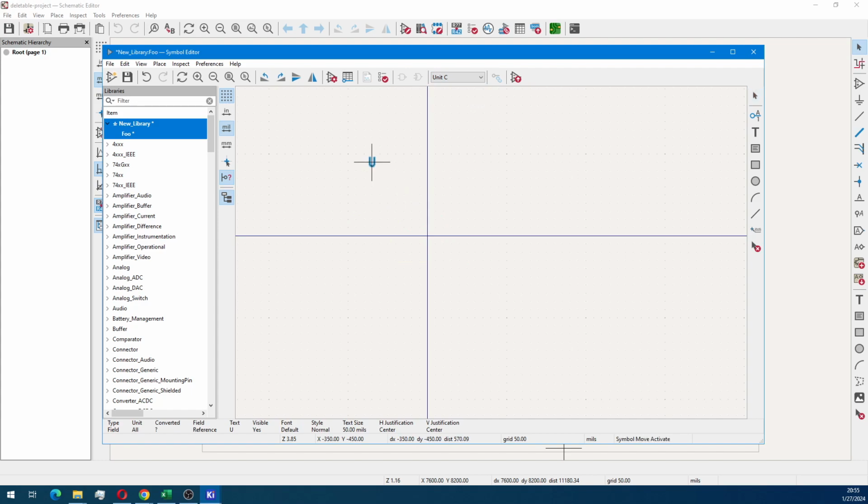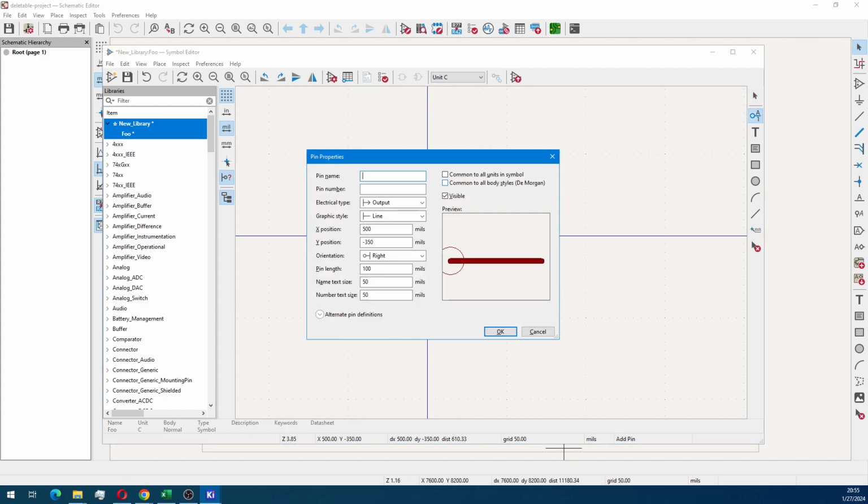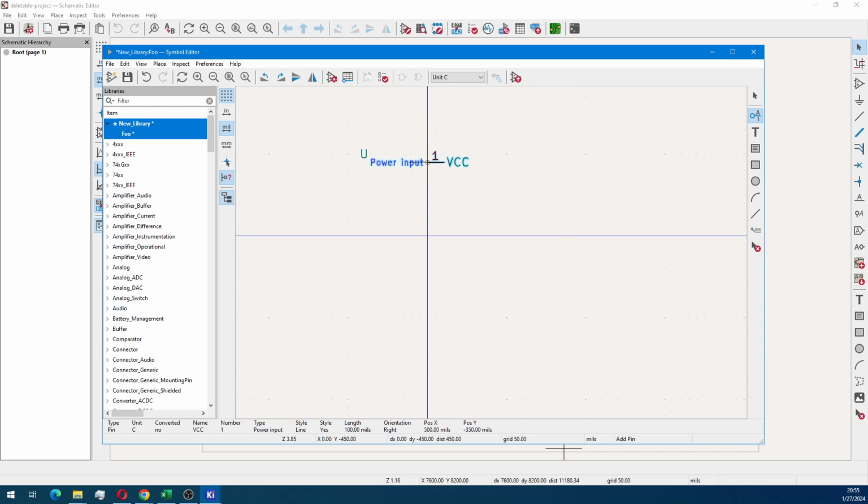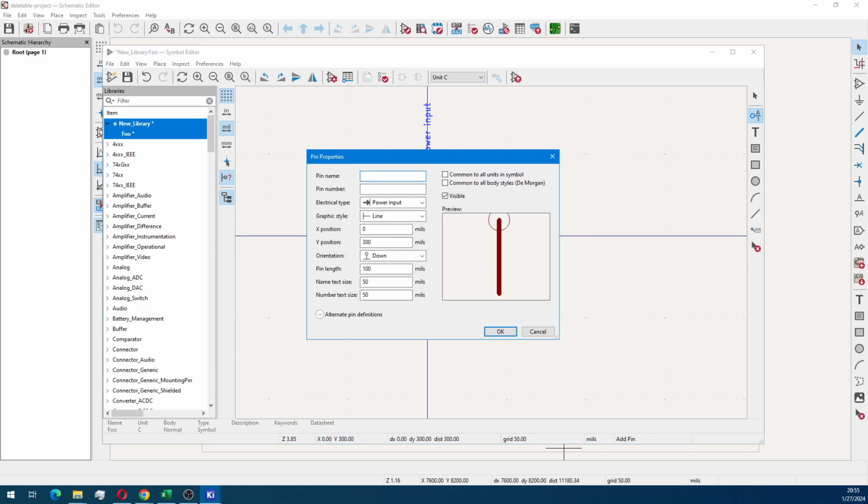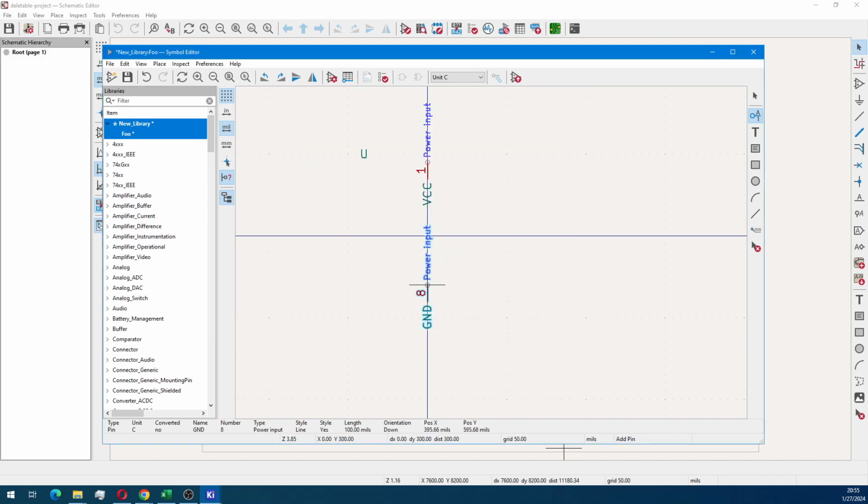And then once again at the top, I'm going up to Unit C and just creating 2 power pins. Traditionally, your 2 power pins, or if there's even more power pins than that, those will be a separate unit. So for example, in the Pine64 PinePhone, if you look at the schematic that they put on their website, that processor, which has, I believe, something like 300 or 400 pins on it, is broken out into multiple units, and the power pins essentially are their own unit.